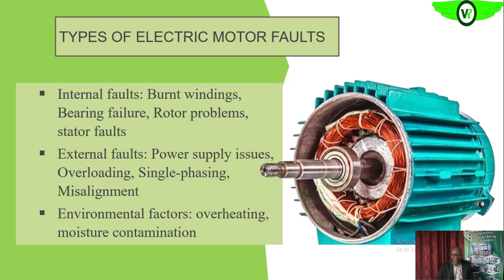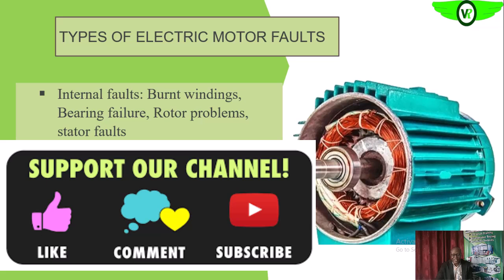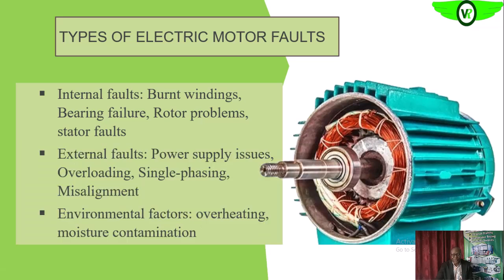There are times too when the motor is not designed to operate in an environment with, say, high humidity, so the possibility of water ingress will also be high. Once we have water ingress into the windings, we all know that it will reduce the insulating capacity of the insulating materials used on the winding, and thus result in winding failure and in failure of the electric motor itself.